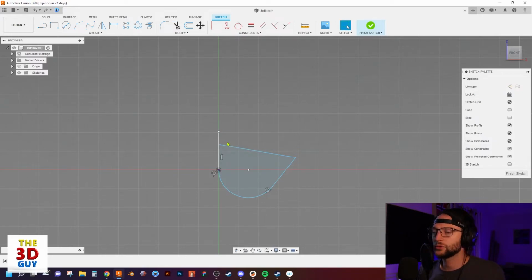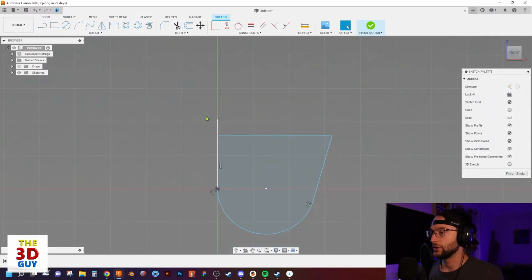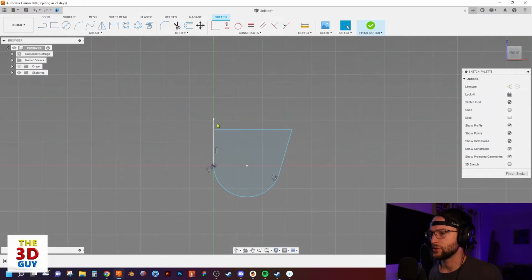But again, this is one of those features that almost always I am actually going to manually put in perpendicular. It's not deciding to snap right now. So in this situation, there we go, right there. You can see as I'm sliding it, there's a couple of spots it's wanting to lock to. You can actually bring it in to right there, and it'll snap that little right angle for a perpendicular. So that's the quick way of doing it. Typically, it would snap on a lot faster. I'm not sure why it was connecting to all those other areas pretty quick. So we will get rid of that.